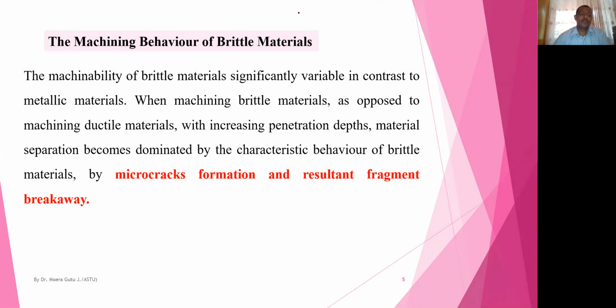Well, if you see the machining behavior of brittle materials, what the brittle materials will do during machining, we will see in this category. The machinability of brittle materials is significantly different in contrast to metallic materials. This means the hard materials, ceramics like glasses, are significantly different from metallic materials.